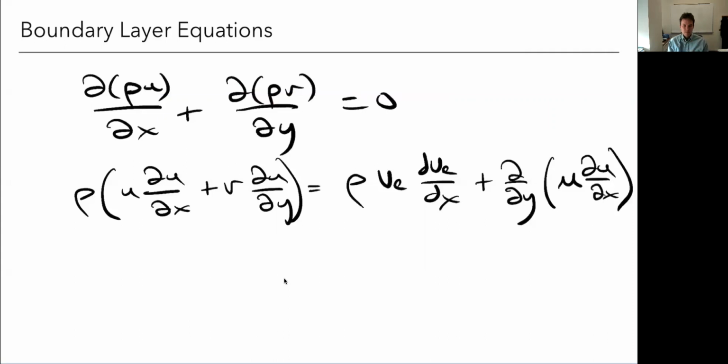Okay, so this is actually, maybe this should be rho edge. So this is my boundary layer equations. This is the differential form. And if it's incompressible, a lot of this is going to simplify greatly. So if it's incompressible, for example, these densities cancel out. This cancels out. This one just becomes nu.